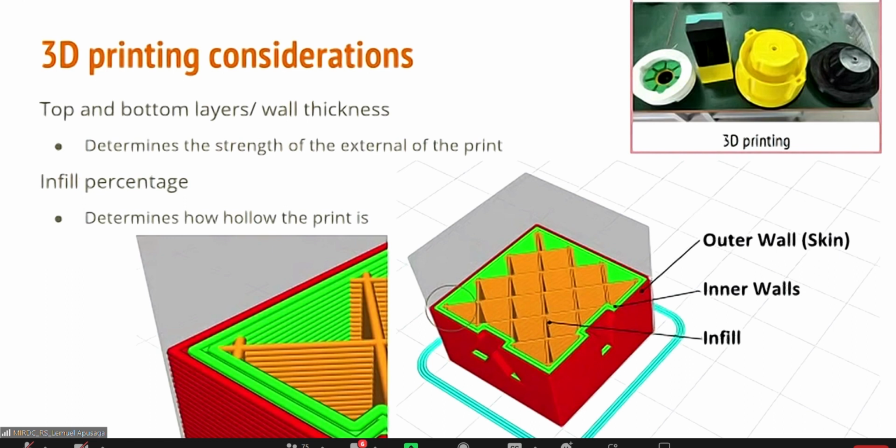If it's just a simple jobbing part that might require like 50 or 100 pieces, you set your parameters for 3D printing in such a way that it's just enough for you to be able to make those 50 pieces. You do that by defining the wall thickness of the prints and also the infill density. If it's of a bigger volume, then do 100% density to make it really rigid and solid. But if it's just like 5 or 10 pieces, you can get away with just 40 or 50% density.